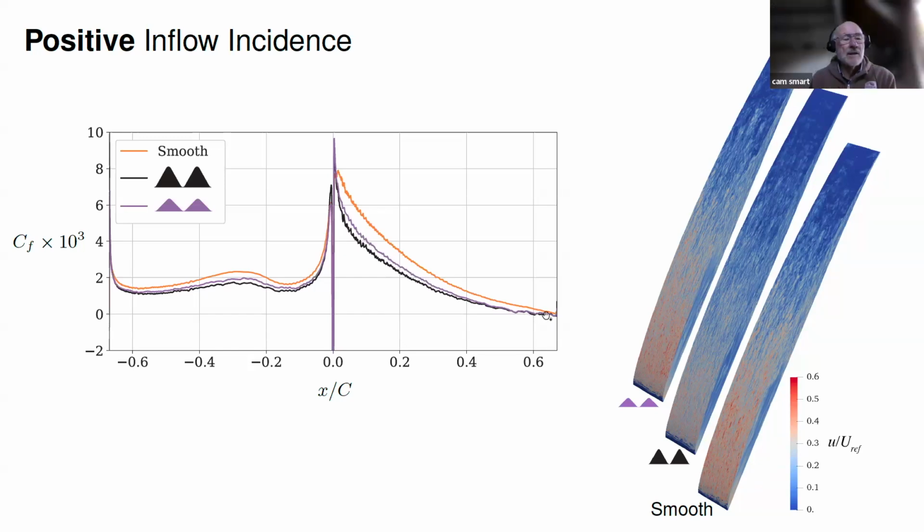Oh, yes, okay. So the question was whether the riblets could increase the operability of the engine, to try and cope with stall. I didn't see it here. It didn't seem to promote attachment. It will do that if placed more upstream, so it'll make the flow turbulent and kind of stick to the blade, but at the back it was still separated, potentially causing even more separation. So it didn't seem useful for that.